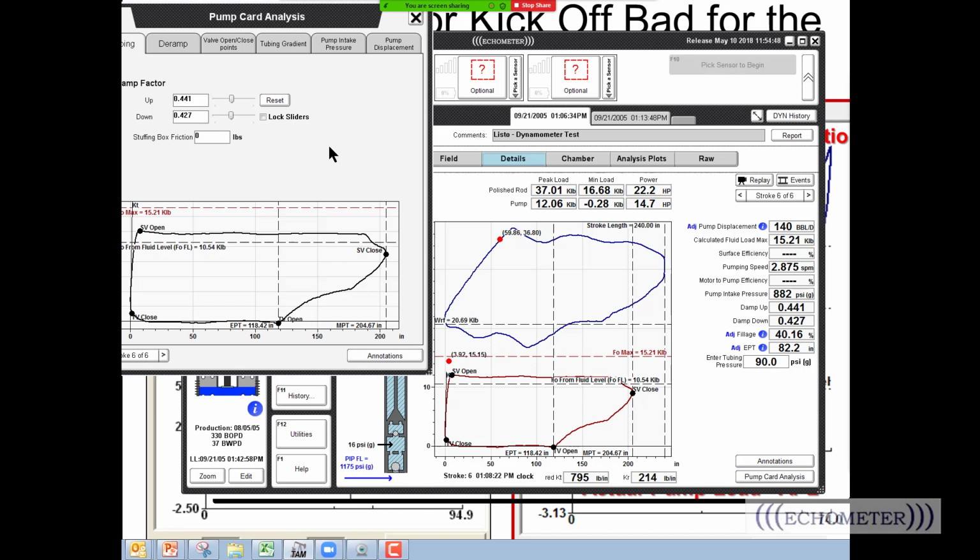But then if you set the pump in the horizontal, the pump will still work just fine, but you'll have 2 times the number of failures that you would if you had the pump above the kickoff point. But if you set the pump in the curved section of the wellbore, then you typically have three times the failures. And I have that reference. I think that reference is probably in the paper that's on the cover slide of this PowerPoint. So there is a reference for that. It's in the paper. If you can't find it, I can email it to you if you just email me.